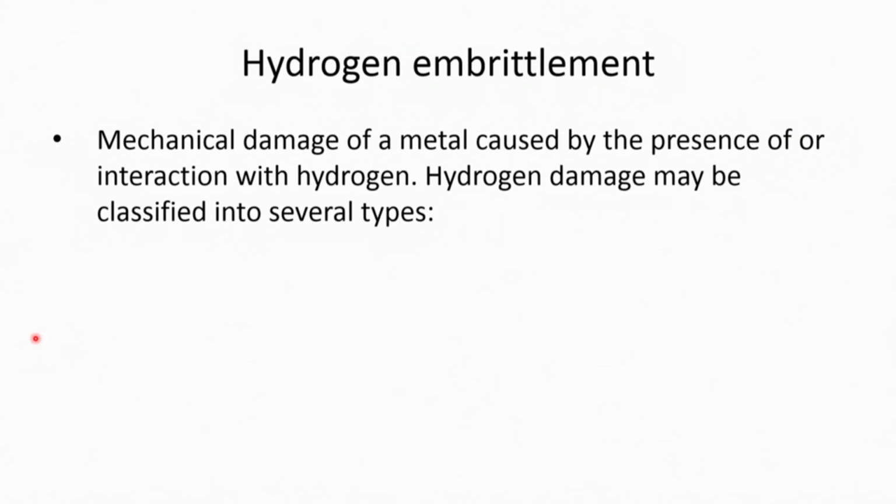You will find that hydrogen is a very dangerous species because it can cause failure by reacting with the surface and forming hydrides. Those hydrides are not good because they are very brittle in nature. In some metals, hydrogen species can diffuse in as atoms and change from atomic to molecular hydrogen deep inside the metal.